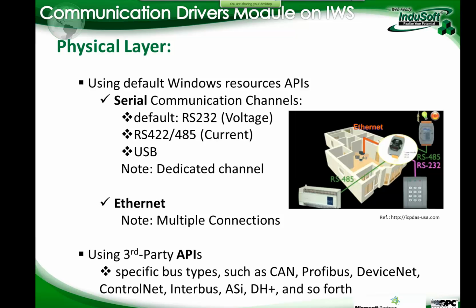Or more specifically, you could go with RS-422 or 485. The main difference between these two channels is RS-232. I'm going to talk about the differences a little bit ahead, but with RS-232, you have a distance limitation. With RS-422 or 485, you can go longer distances, and you can also have multi-drop, while RS-232 is point-to-point communications or